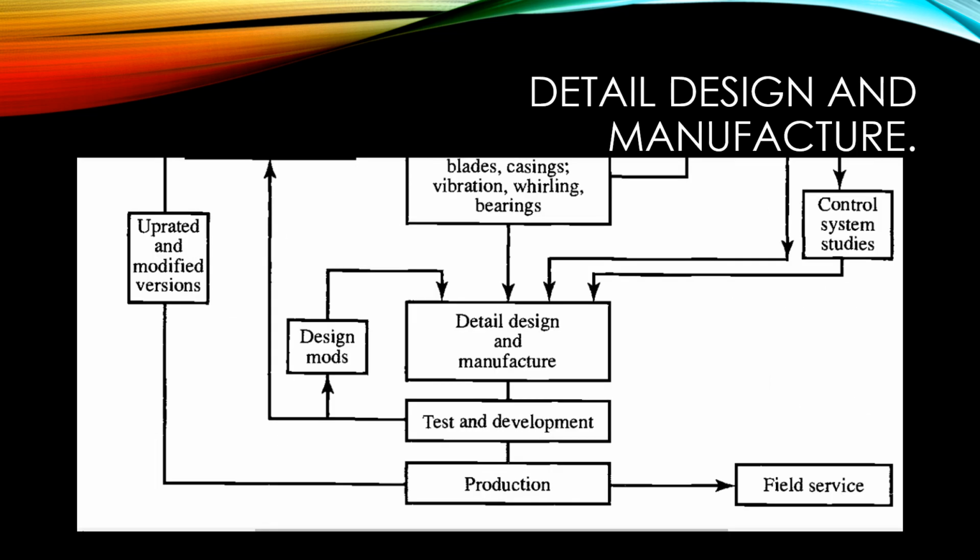Detailed design and manufacture. At the same time as the mechanical studies are proceeding, off-design performance and control system design must be considered. Off-design operation will include the effects of both varying ambient and flight conditions and reduced power operation. When designing a control system to ensure the safe and automatic operation of the engine, it is necessary to be able to predict parameters such as temperatures and pressure levels throughout the engine and to select some of these as control parameters.